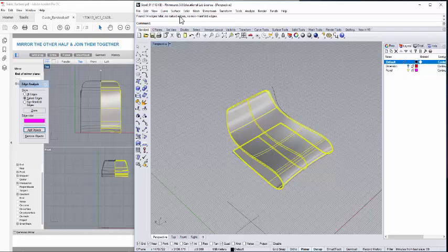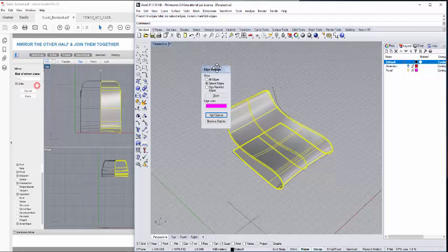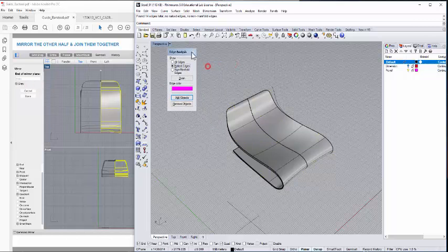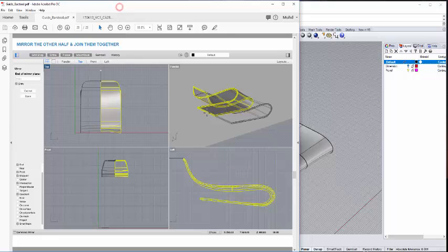Because why? There is no holes. Alright, there's no manifold edges. Manifold edges meaning, let's say for example, you have a surface and then it's twisted and all. So there's no naked edges, there's no manifold. There's also volume. So this guy here is a watertight model. There's no issues. Okay, let me just close this, go back again.